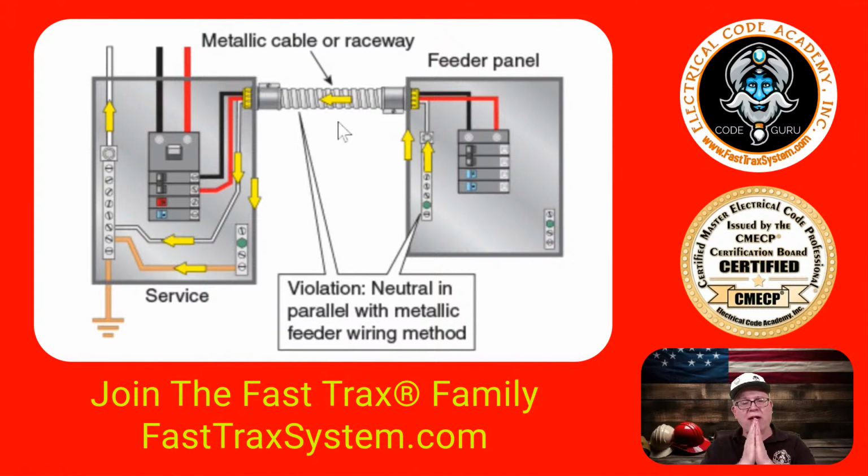But what we wanted to point out with this illustration was that if you just remove the screw, it doesn't remove the issue, because now we still have to make sure that that return path for the fault current is either a raceway or a cable that is allowed to be used as an equipment grounded conductor. And as we said, this is obviously not MC cable. This is obviously not AC cable. The other types are limited by the overcurrent protective device protecting the conductors in the cable, usually to 20 amps or less. So in this scenario, you have a problem.